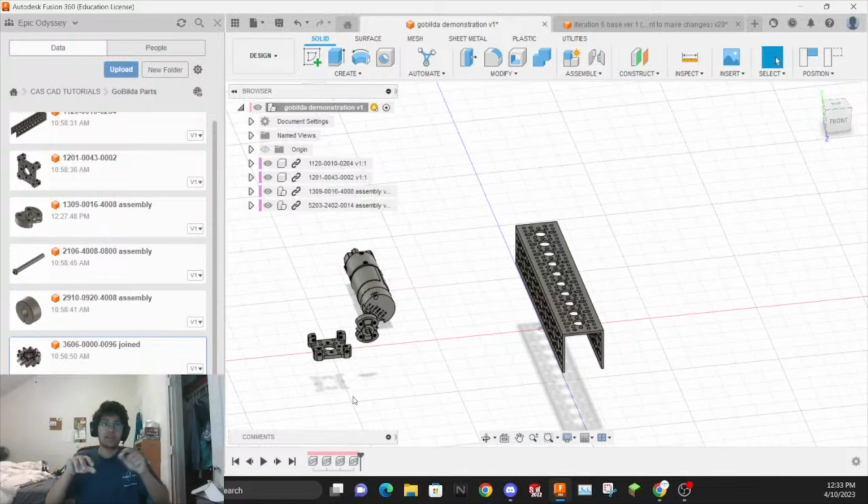It either is a direct swerve drive, which has one motor for changing the swervy part and the other motor for driving the wheel, or you have a coaxial swerve drive, which has two motors, one that directs a top gear and the other that directs a bottom gear. As it spins a motor and changes the position, or spins a wheel and changes the position of the wheel. So those are really cool, but they're really complex, and I really wouldn't recommend it right now.